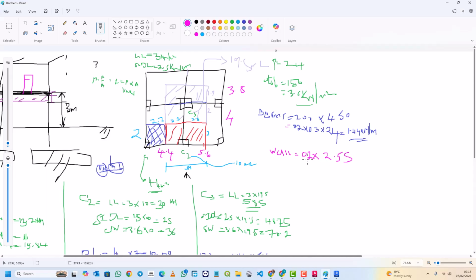Now, when you multiply length times length, you will get length squared. So this means you will get the area. But we want to get this into a load, kilonewton per meter. So to do so, you have to multiply this by the density of the wall. In essence, I always assume the density of the wall to be 18. But please go with what is supposed to be.